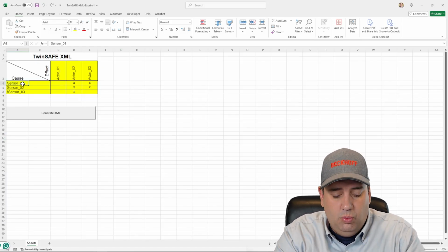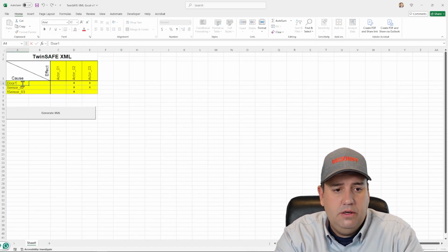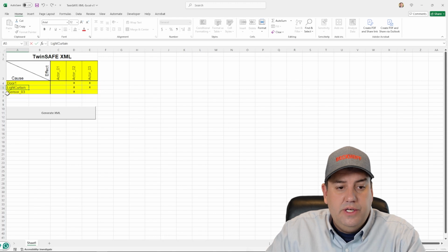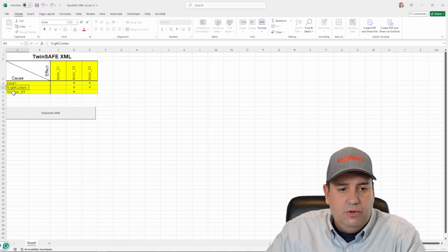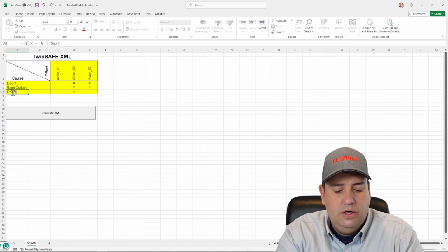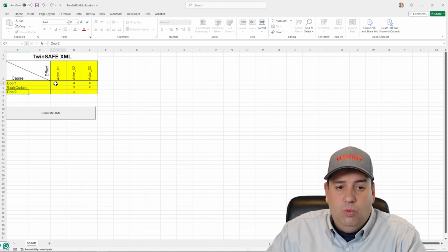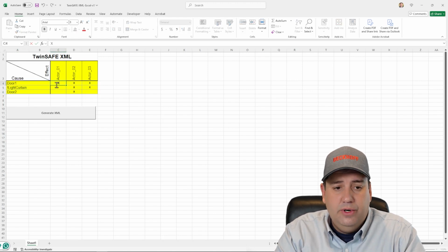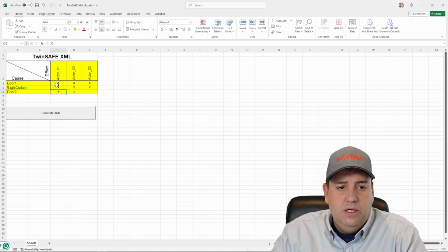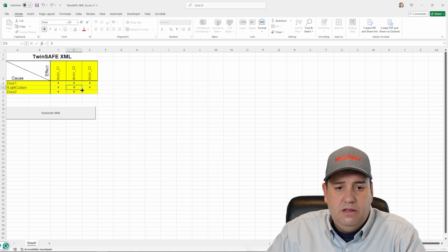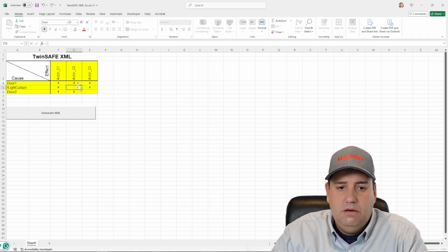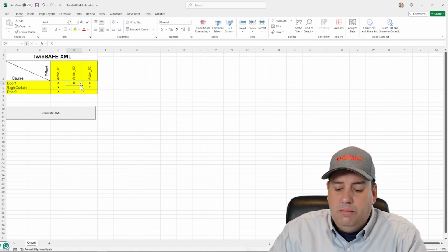So let's make some changes. Let's change sensor 1 to door 1, sensor 2 to light curtain, and we're going to negate light curtain. And we'll change sensor 3 to door 2. For actor 1, let's assume that all 3 must be true. For actor 2, let's say that the light curtain is violated, but door 1 must also be off.